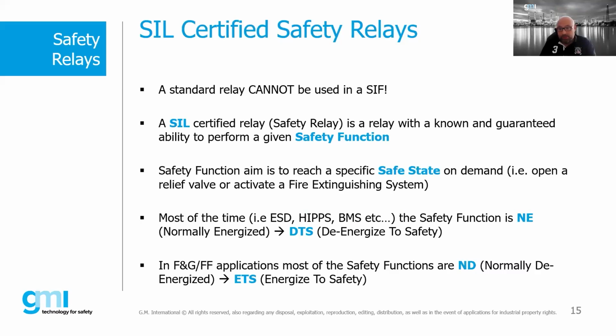Which are the differences between a standard relay and a safety relay? Yeah, of course, in the market there are a lot of relays. You may find different applications, different solutions, but most of them are standard. They are not safe. So a SIL certified relay is a relay that has a warranted ability to perform a given safety function. So basically, it's a really basic product, but it is safe. So when you ask it to move and to open or close, there is a really high probability that this safety function will be performed.